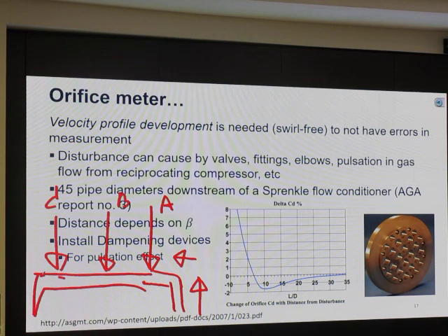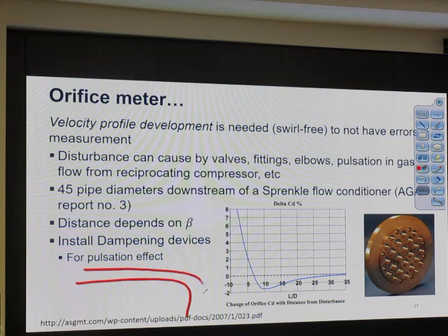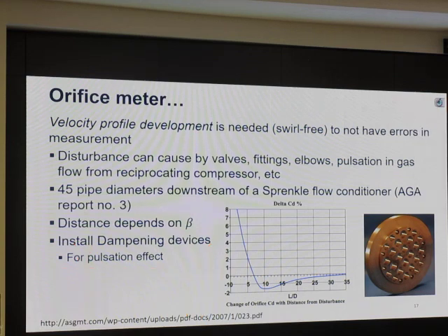Most of the time, whatever happens downstream should not do anything with upstream, but it can. There could be two-way communication. Most of the time what we worry about is enough length for the flow to be fully developed. So the location should be far away enough from the entrance. If we cannot do that, we may put this thing in.